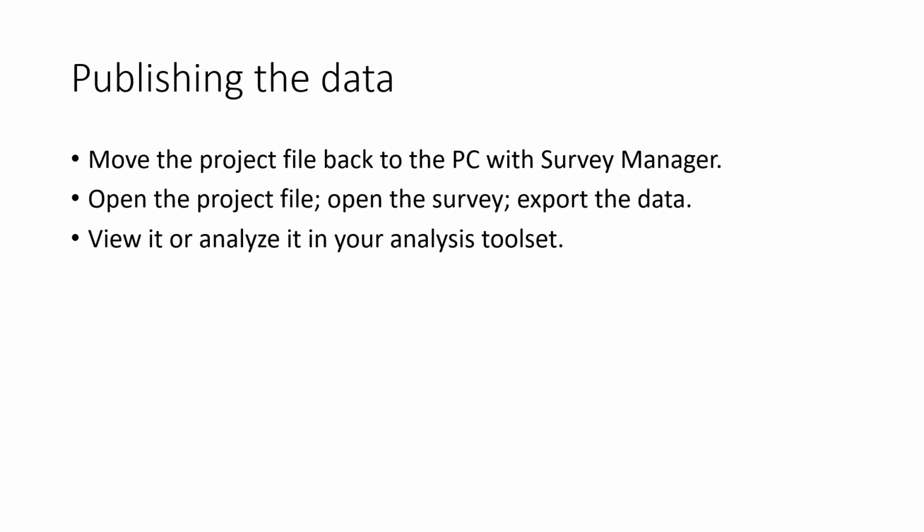Once you've collected all this data, you'll move the project file off of the tablet back to the PC with Survey Manager running on it. You'll open the project file, open the survey. You should find data in it, of course, and you'll export the data either to CSV or to GDB or some other supported format. And then you can view it or analyze it in your analysis programs. That could be MagPick, MagMap, Surfer, Oasis Montage, whatever you're using.